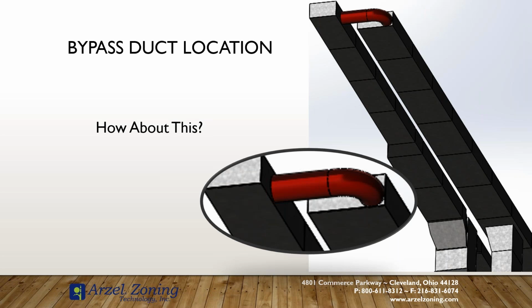Your supply air, you're losing your back pressure and you're forcing your greatest amount of pressure back into your lowest amount of draw. And now that's going to turn your return airs into supply airs. So if that area of the home isn't calling, you've pressurized your return airs, you've turned them into supplies, and now you're forcing air through your return duct out into that zone that's not calling.